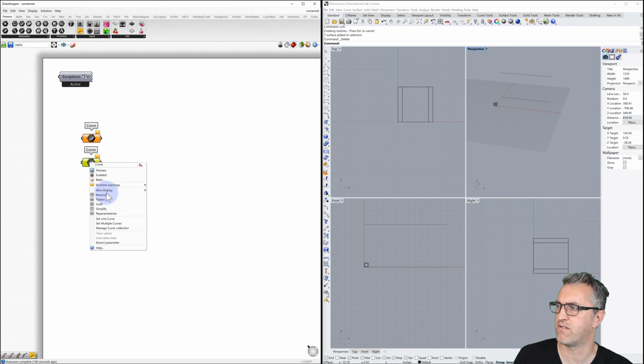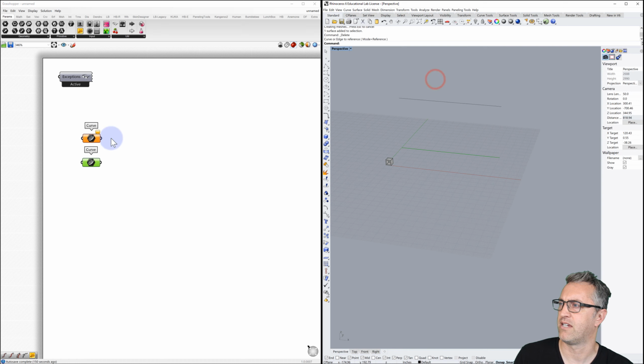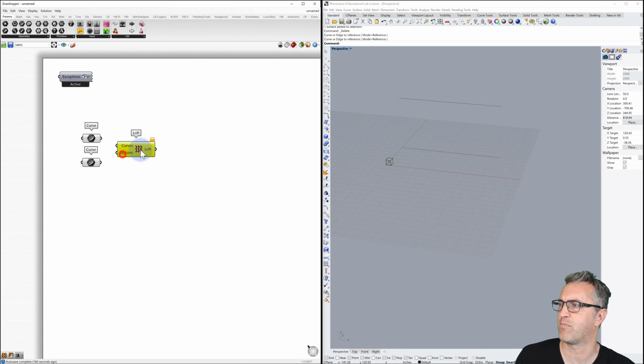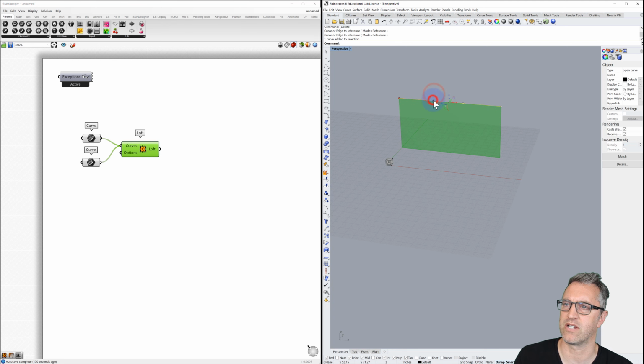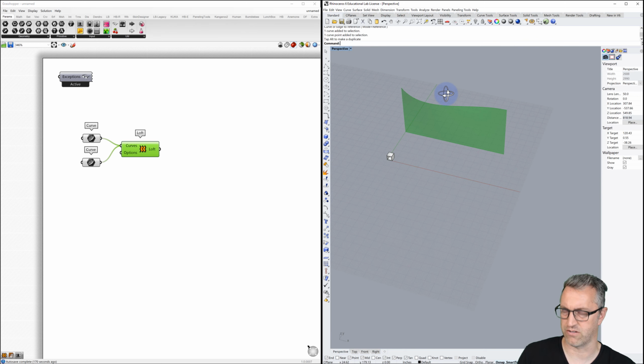So the bottom curve, we'll set 1 curve and select that, and then right click, select 1 curve, and we'll pick the upper curve. Now we have these, and let's do the loft in Grasshopper. Add the first curve, hold down shift, and add the second curve. So now we have this. What's nice is that we can manipulate that, and it'll stay parametric.